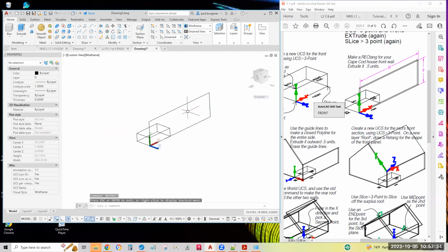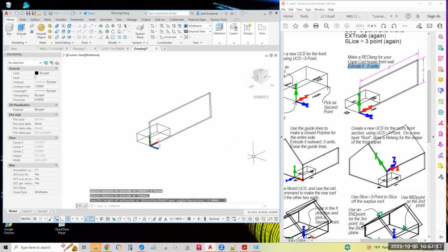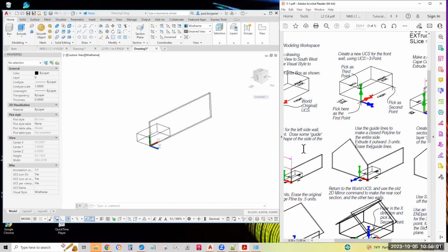There. Up, we want to extrude it 0.5 units. Click extrude, select the rectangle, enter, point your cursor in the direction you want to extrude in, at 0.5 for a half a foot thick. So that'll be the front of the house. Later we might cut a door in and build a porch and steps and all that, time permitting.